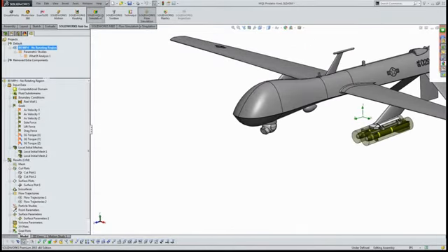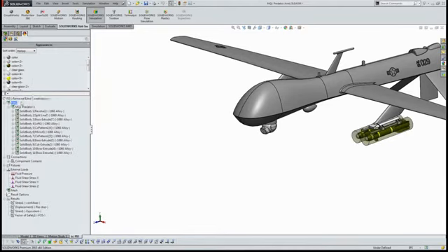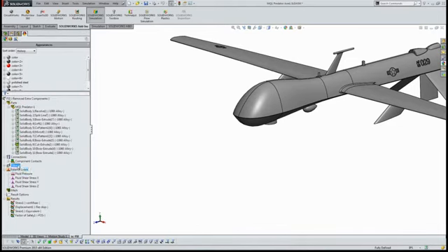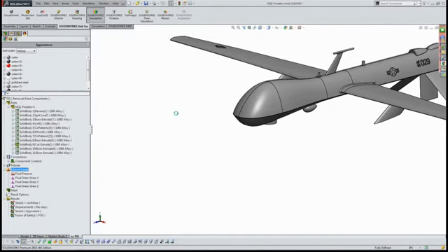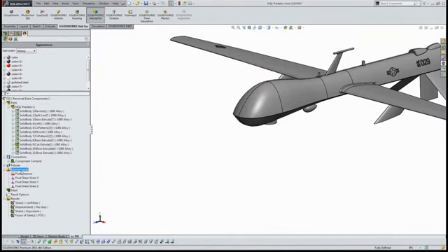So let me add SolidWorks Simulation because I want to show you guys another really interesting thing that you can do. So basically, I've turned on the FEA solver, and what I'm doing in the FEA run here is I'm actually pulling the loads from the fluid run. So I'm saying, look, I want to grab the pressures from that flow simulation, and I want you to map those pressures onto my structure here.